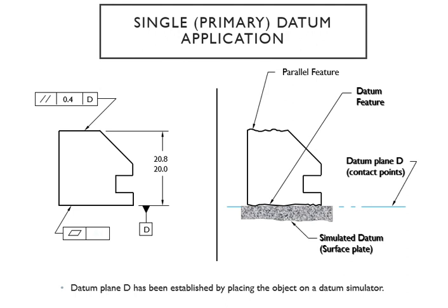Again, why do we have to do it? Because that's imaginary. Physically, if you don't have a simulated datum, in real life it's a block, which we call a gauge. It's just a tool, just a little block. Without that, we wouldn't be able to get the contact plane.